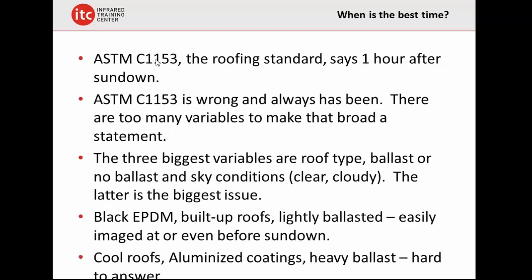Now, there is an ASTM procedure for doing roofing inspections. There's ASTM C1153. I don't know the current edition of it. It says the best time to do a roofing inspection is 1 hour after sundown. ASTM C1153 is wrong. The reason it's wrong in that statement is that there are too many variables. There are too many different roof types and too many different sky conditions. That is just too broad a statement. Interesting. I did not realize that.